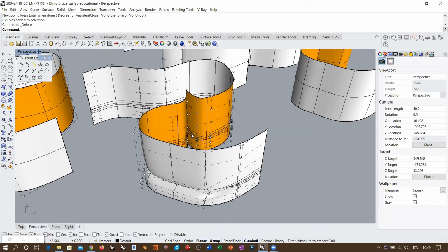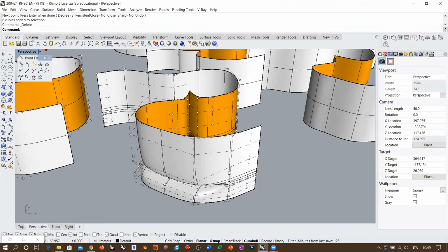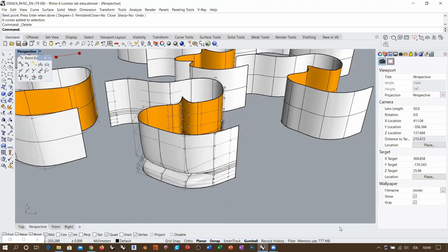Whatever you do inside your surfaces will propagate horizontally and or vertically. Let me see what's the question. So in general, to create creases on surfaces, we work with kinks directly on the surfaces instead of creating the kinks on the curves that we generate the surface from. Exactly, because if you visually create kinks on the curves, then you will get polysurfaces.